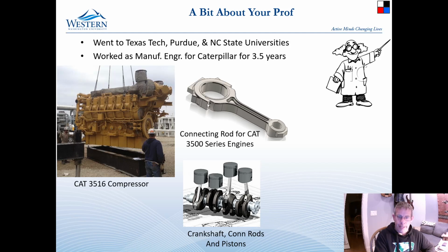The joint right here between the cap, which is this part, and the rod, which is the rest of it, is a really critical joint, and if it has any extra space in there at all, it will work itself to death as this cycles over and over and over. It's also a pretty hard thing to create because the cap is a little bit flexy, so when you put it in a fixture and spin it up to speed to create this joint, it will actually open up.